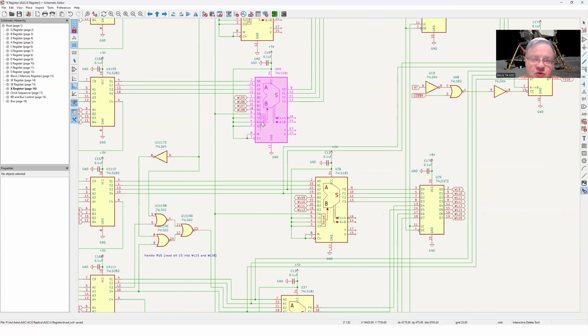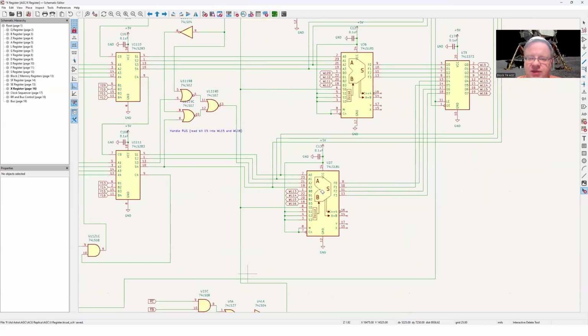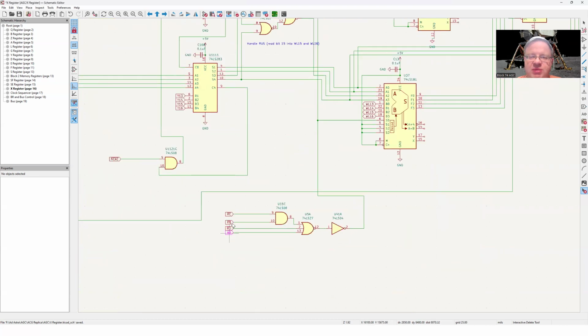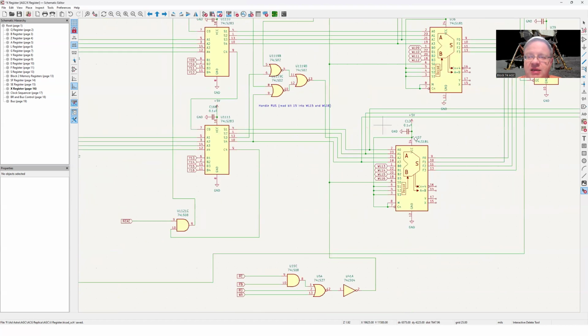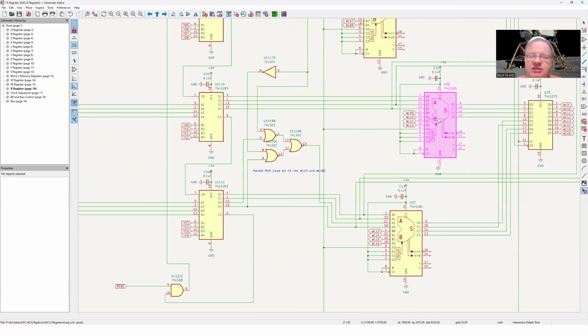Plus, we'd have to have some control logic because we only want to perform that ORing of the write lines when we have this sequence of sub-instructions. So we'd be looking at a lot more than 4 chips to build out this functionality. Just to save a little real estate on the boards, we're going to use these ALUs. And since I was able to secure a surplus of about 15 or 20 of these, I've got extras lying around, so why not?